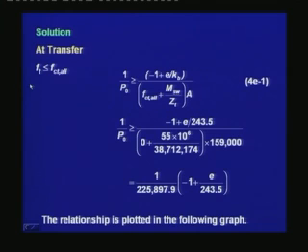The first inequality relationship satisfies the condition that at transfer the stress at the top should be less than the allowable tensile stress, which is fct allowable, and corresponding to the inequality relationship, we are substituting the values of Kb, fct allowable, Msw, Zt. Now, since it is a type 1 section, fct allowable is equal to 0.